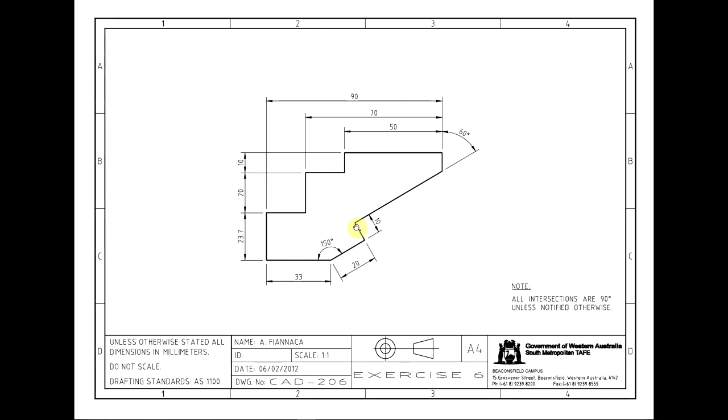Once we get to this stage, we're just going to pull that up and then use object snap tracking. So with object snap tracking, the whole idea is that you can move over a snap point. So in this case, it'll be an end point, and we can track straight down, and we keep pulling our mouse straight down until you see a green dotted line here, and that will snap to your 30 degree angle, and that gives us that length and that height. So you'll then click there and close to finish the drawing, and that's pretty much it.